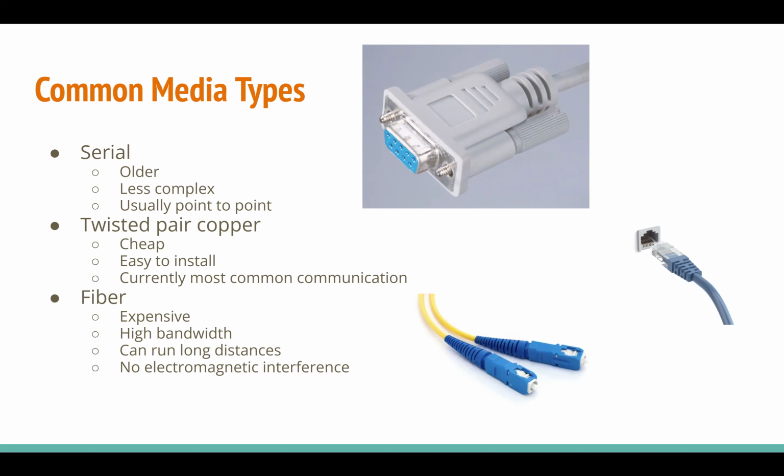The inside is either glass or plastic. And you know how when you bend glass or plastic back and forth, it develops that white line and then snaps at that location. You do that once with a fiber optic cable, it's done. It's broken entirely. Those two reasons are why we don't use fiber optics in the home. We still use copper, and that's going to be true for a very long time. I wouldn't be surprised if we never really see fiber optics show up in home use, but we use them in utilities a lot because of the lack of electromagnetic interference. So, any questions on that?